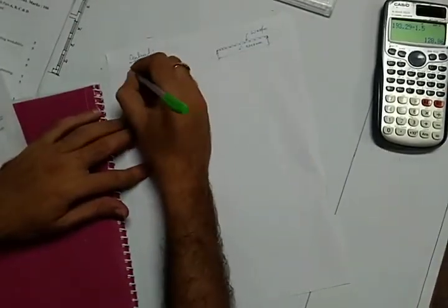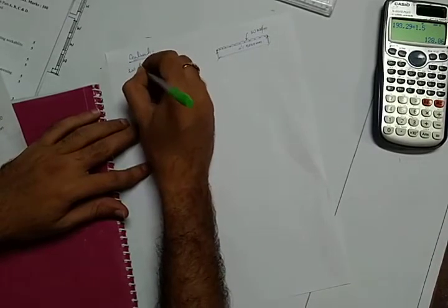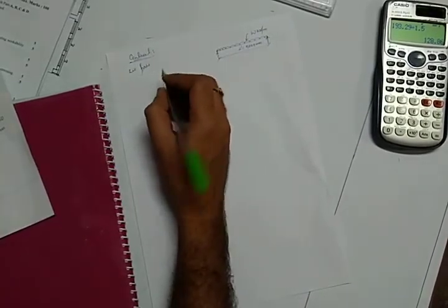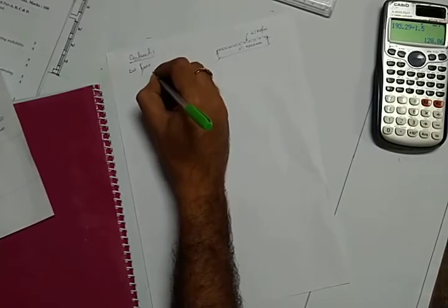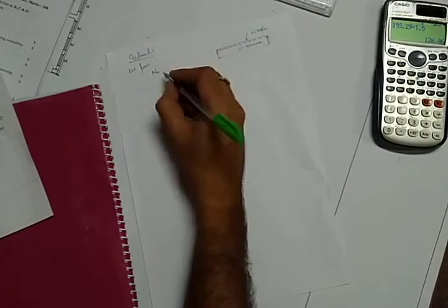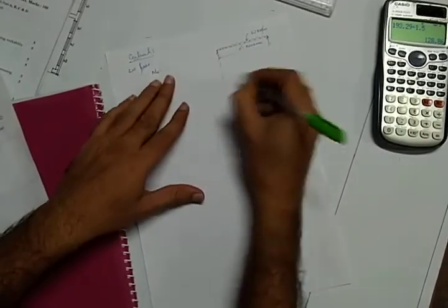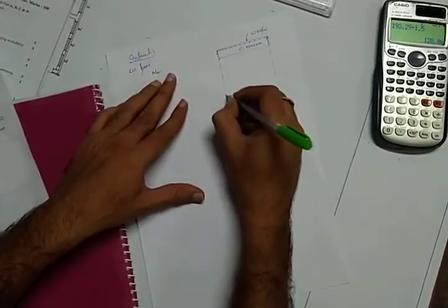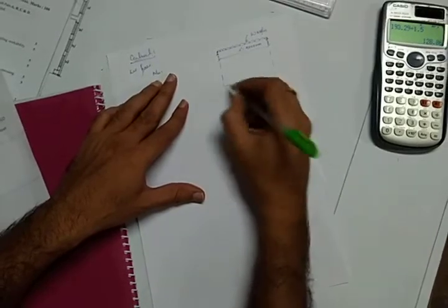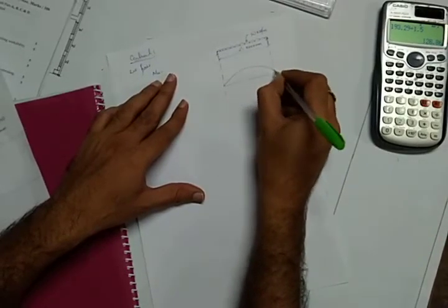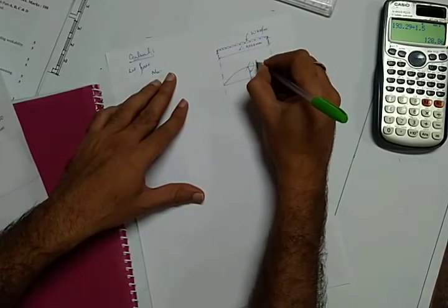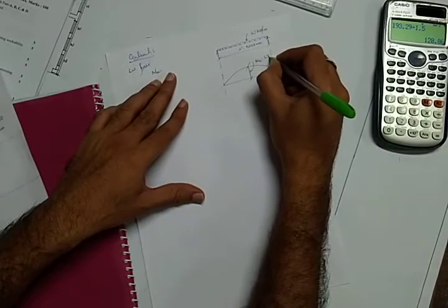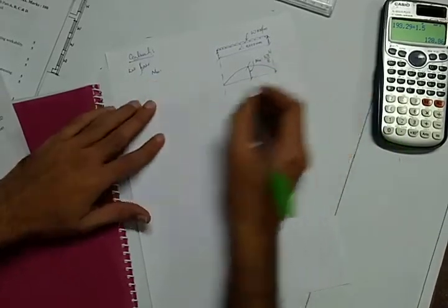So this procedure is followed to calculate safe superimposed load. We have a formula to calculate the moment. Maximum bending moment occurs at the center. So if you project these lines, we will get a bending moment diagram like this. So this is the maximum bending moment. We will call this as mu itself, and the formula is WL square divided by 8.